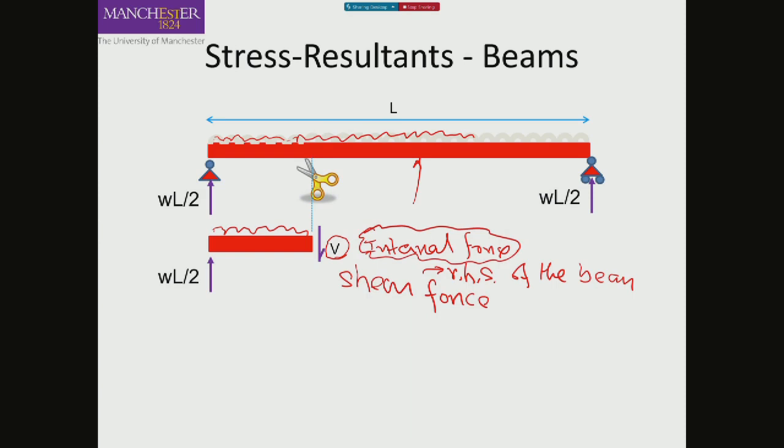So how do we know the amount of it, the direction of it? It is again using equilibrium. We make a virtual cut and then we see what sort of forces, or the support system, I need from the other part to keep this side under equilibrium. Now, of course, the left-hand side in return gives to the right-hand side exactly the same amount of force in the opposite direction, using Newton's third law, equal and opposite.